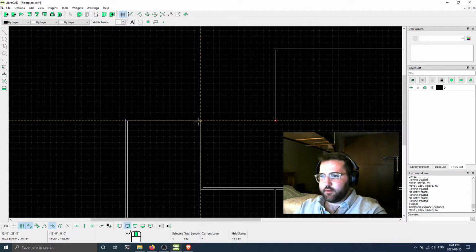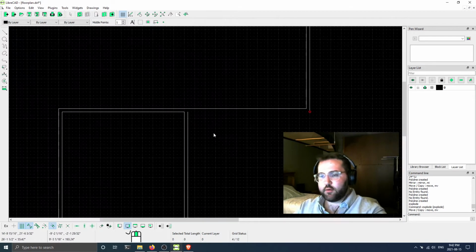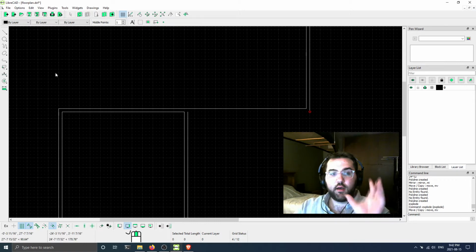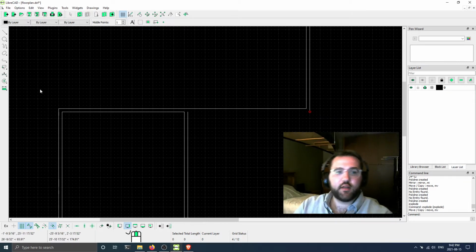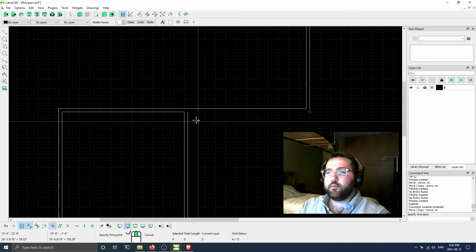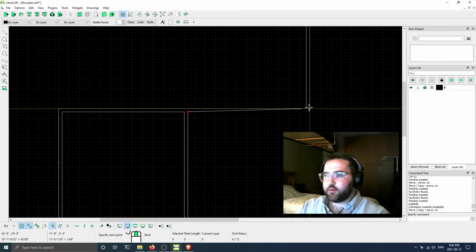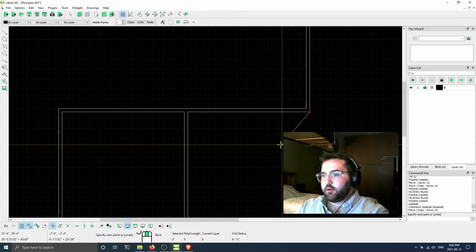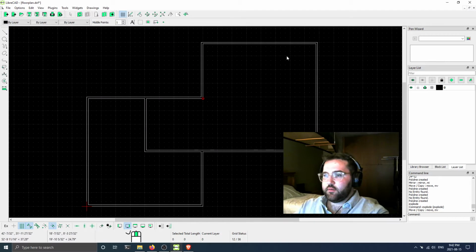because I'm not actually going to use polylines really for this part of the drafting work, except for when I want to offset stuff that has angles, because doing that with Polyline will mean that you won't have to use the trim tool as often, and the trim tool can be kind of slow, although very useful when doing certain types of drawings. We'll demonstrate it later. So there we go. I now have a continuous wall segment. So this is the first floor.